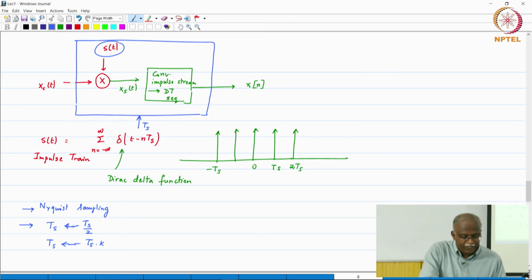So, in a nutshell, multirate signal processing is about taking the foundation of DSP, where you are very familiar with the discrete time processing of a discrete time signal. For us, it is very important that we also be able to work with changing the sampling rate, keeping the underlying link to the continuous time signal, because if you change the sampling rate arbitrarily, you could run into artifacts or impairments such as aliasing.